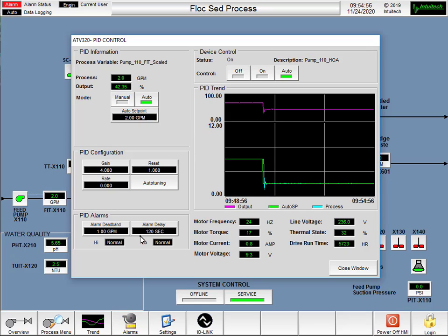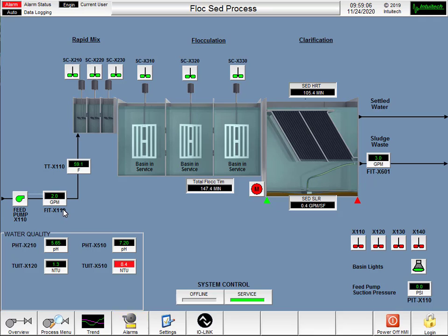The final thing for this screen is there are some readouts on the motor and its VFD. These are mostly diagnostic parameters for determining the state of the motor and its VFD. In regards to the inlet flow rate on the outlet of the feed pump, there is a hard-coded low shutdown alarm that if the system flow rate falls below 0.2 GPM, the system will initiate a shutdown. This is to protect the system from running dry due to loss of feed water.